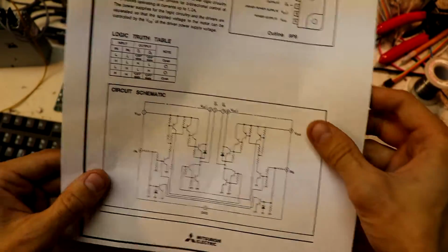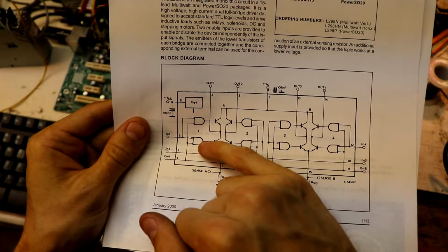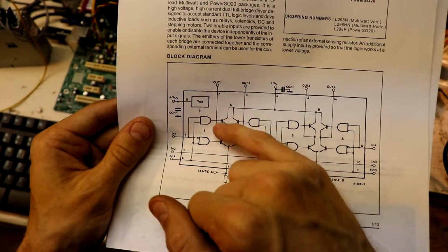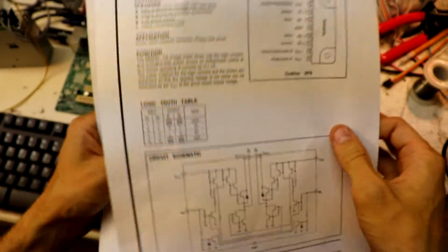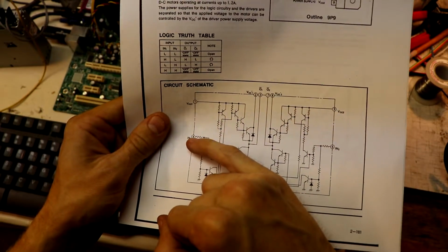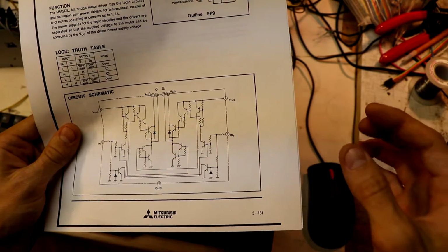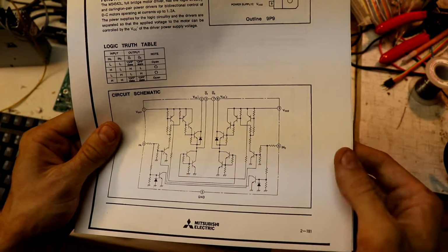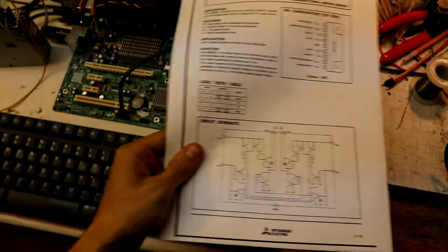What we know from looking at the other schematic is that what the enable pin does is simply turn on or turn off the power going to the motor. So what if, to make an enable pin for this circuit, we simply routed all the power pins to one pin and then took that pin and connected it over to a switch that would be controlled by our enable signal that we have configured in LinuxCNC? That was my idea, and actually, I did it.